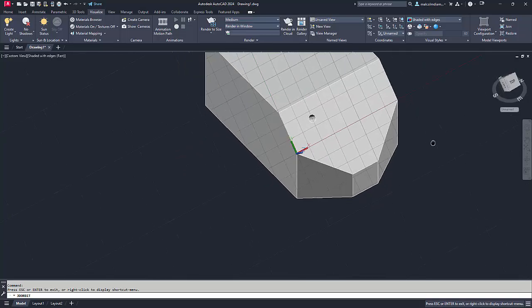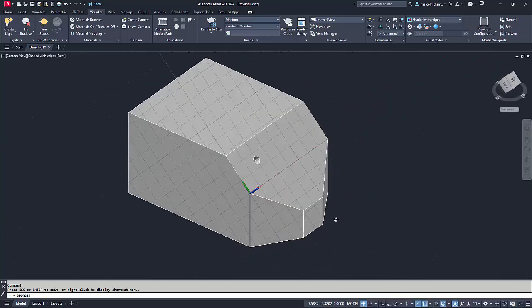Okay, now one last thing to mention. We've just gone through the whole rigmarole of setting up this as a UCS, and even if you go through that whole thing and just move things around, like on the die, where you can actually put spheres and things top and bottom on a certain surface, you could set up 3 UCSs and do front, back, left, right, top, bottom. Okay, and then you could just push the object being symmetrical to the position that you need it. Well, what about if you want to go back to that surface? You don't want to do it all over again.